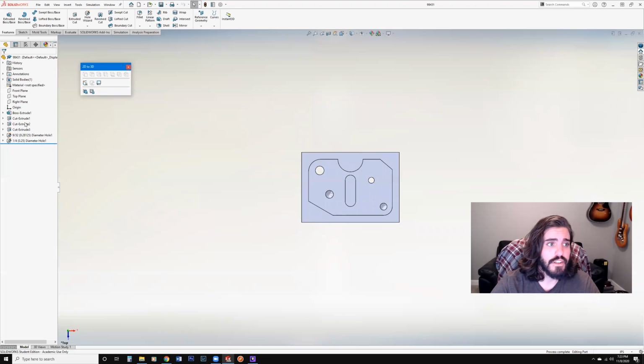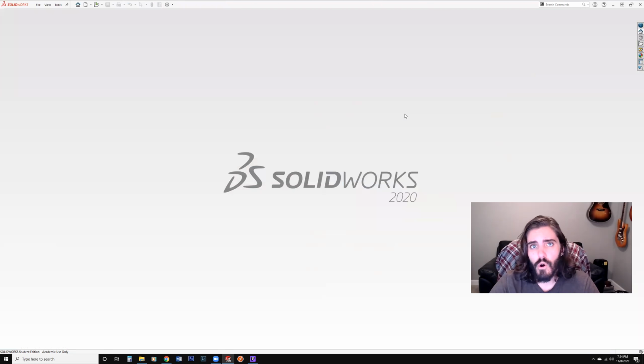The smart solid is any kind of 3D CAD software with a feature tree where you're controlling the different features and the different sketches that you're referencing. If I went to open this up inside of Inventor from a SolidWorks file, I wouldn't be able to, because that native SolidWorks kernel extension file type, which is going to be the SLDPRT, the SolidWorks part, can't be opened in those kinds of software, just like an Inventor native file can't be opened inside SolidWorks. So you have to downgrade it to a dumb solid, and then you have to send it that way.